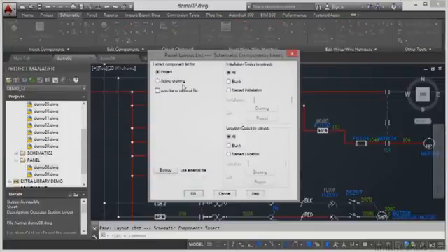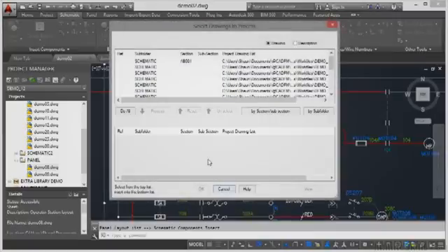Now you'll notice I'm prompted for Extract Component List for Project. That's what we want. I want all of the installation codes and location codes. I can browse to an external file. Now I don't need to do that in this case because I'm looking to my drawings in my project, but I can go there if I need to. The browse option gives me that tool to use. I'll click on OK now, and it prompts me now for the drawings that I want to process.